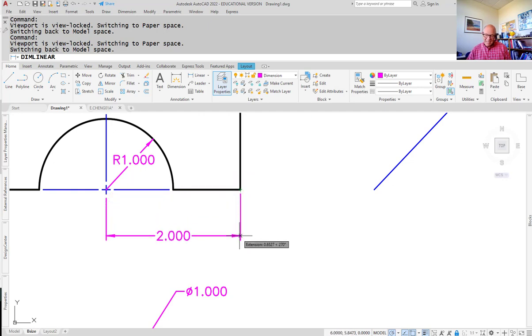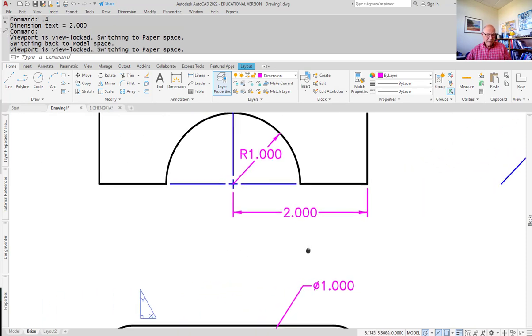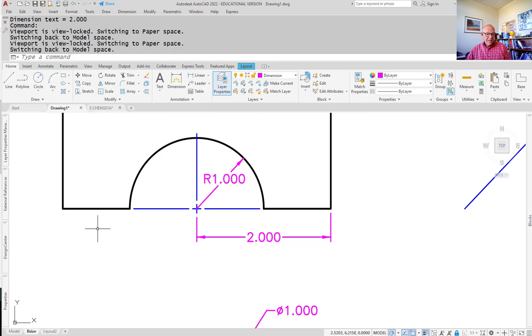I'm going to have that go down 3/8 of an inch, which is what is identified normally, or about 9 millimeters. So I can type 0.375. I can type 3 divided by 8. I could just say 0.4 because that's pretty close, and that spacing doesn't matter as long as it's bigger than the subsequent spacing.